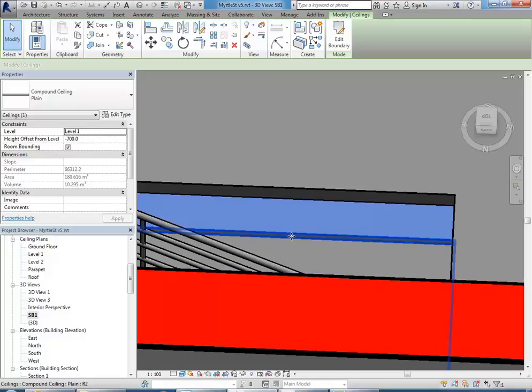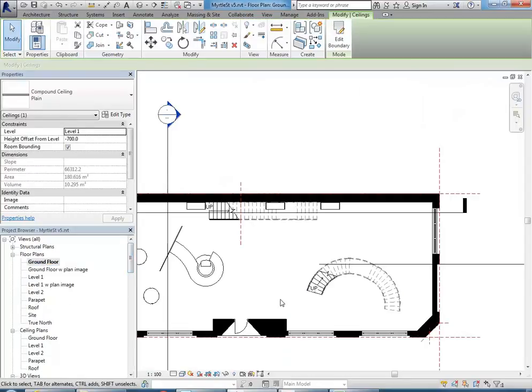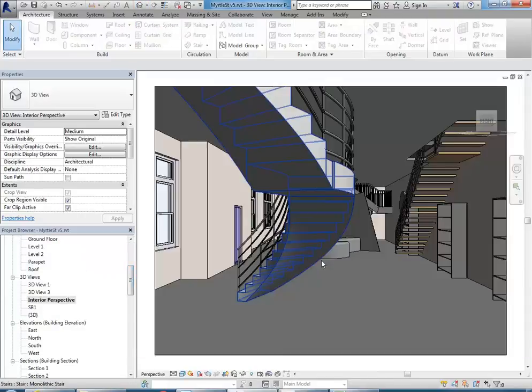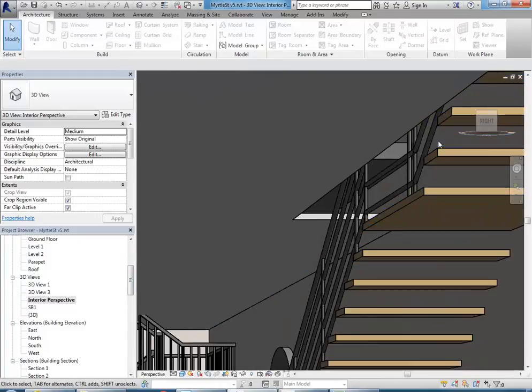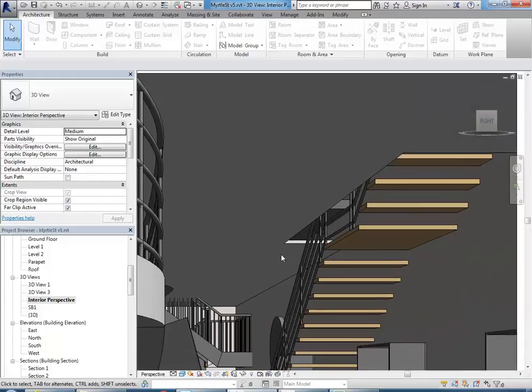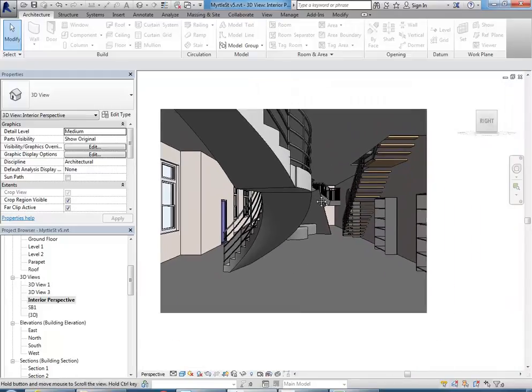What I'll show you when we do lighting is a quick way of making the ceiling thicker. But also remember what you're going to be doing with Saul in Photoshop, and also when we start looking at rendering as well, we're doing it here with Revit. I'll open the perspective view I've got already. You may not see any perspective, so here I can. So I need to think about that. Now I could do it in Revit, but you might find that some of those little details, if you're going to do a lot of the touching up of your perspectives in Photoshop, you can just fix there as well. So it doesn't all need to be modelled perfectly, but just think about those things.